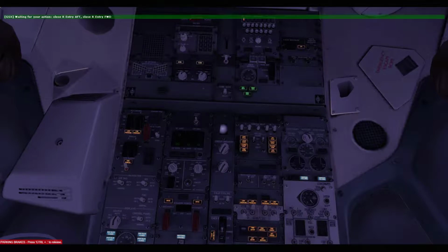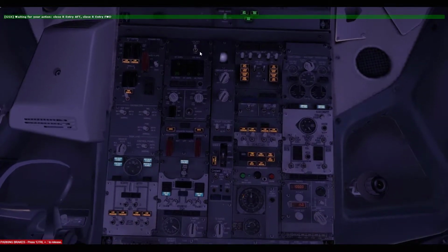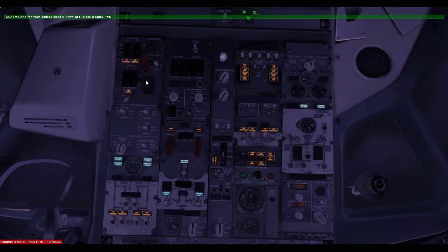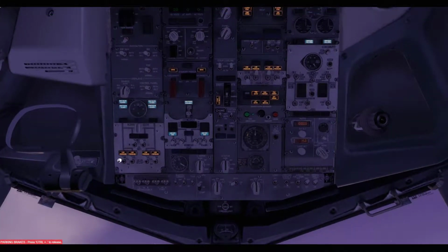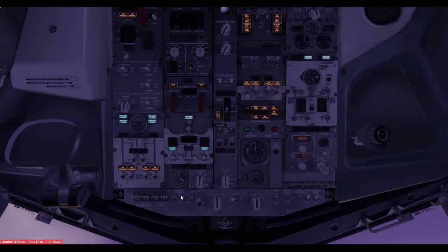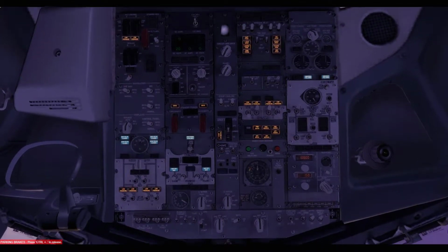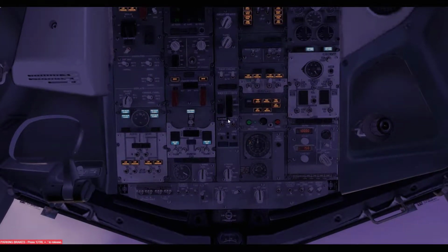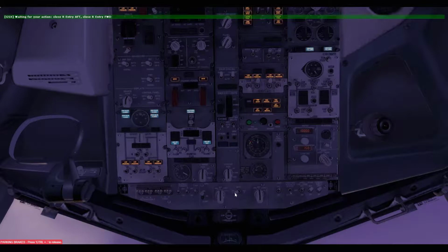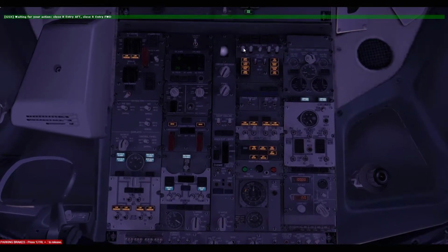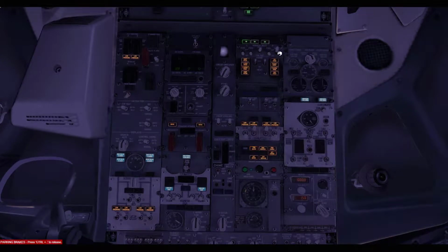Passenger oxygen is on normal. Service interphone is off. Yaw damper can come on. Fuel pumps can stay off for the moment. Now this column and this column is set. Emergency lights, we have done refueling, so signs can come on. We are an odd flight number, so left ignition is okay. Let's put the window heat on,